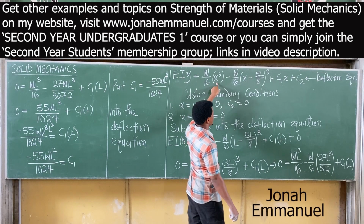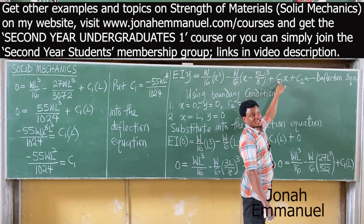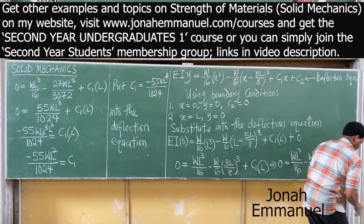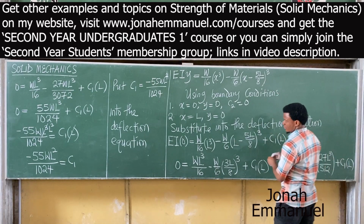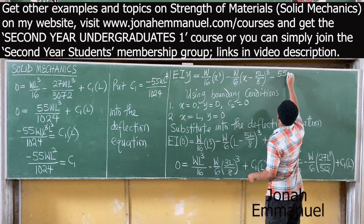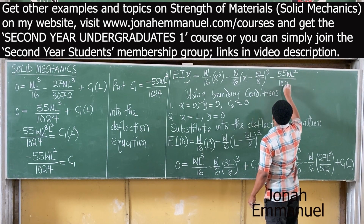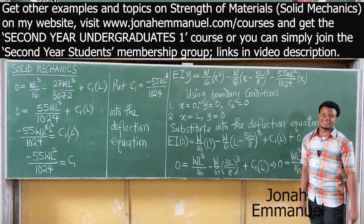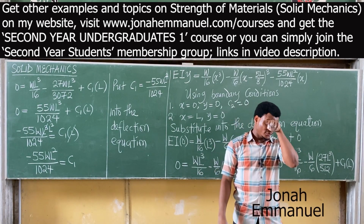EIY equal to this minus this. Where I have C1x, I'll take up the C1 and put the value, then attach x. C2 is 0. So C1 is minus 55 WL squared all over 1024. So C1x, this plus C2 0. I've gotten my answer for the first one. See how fast we are. So the A part has been solved.